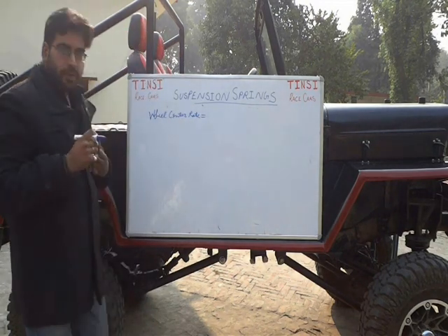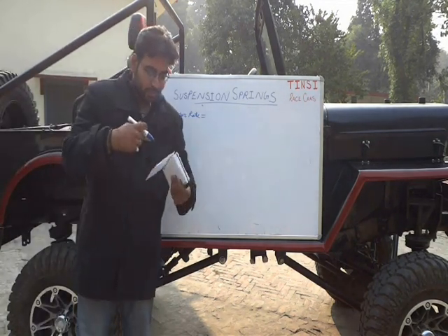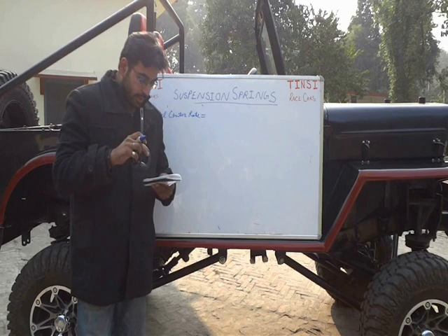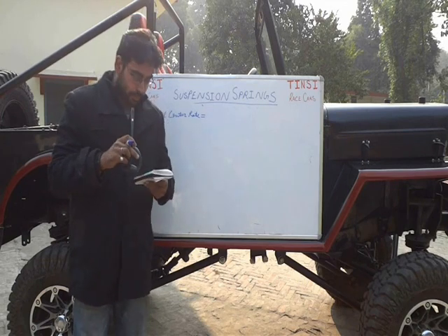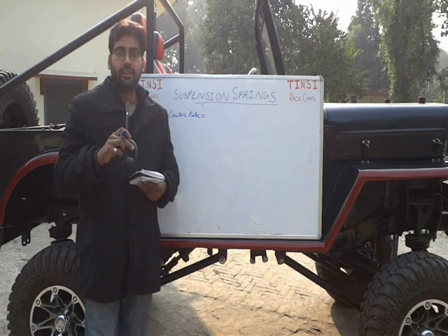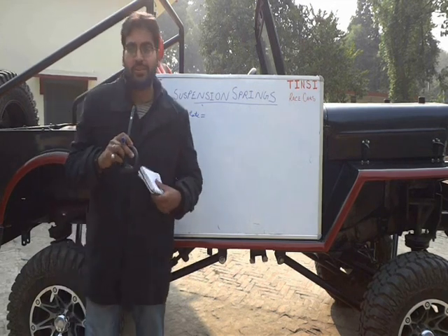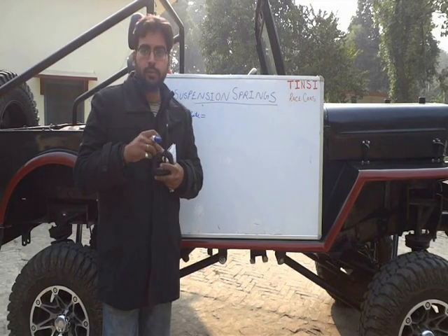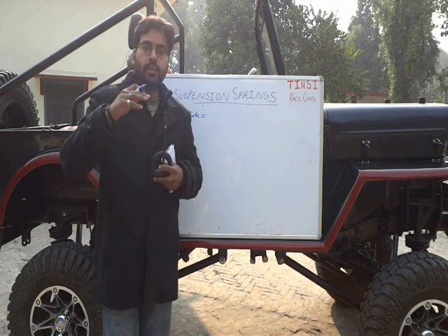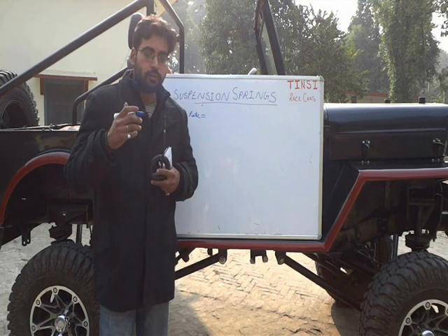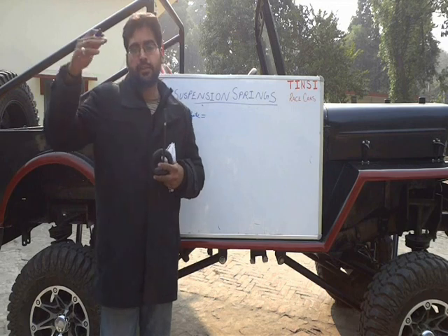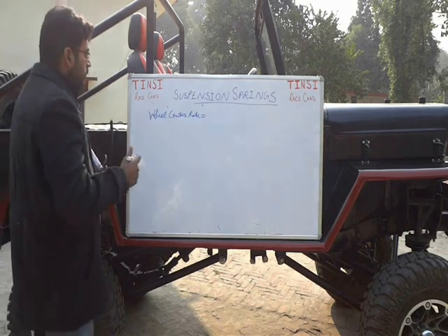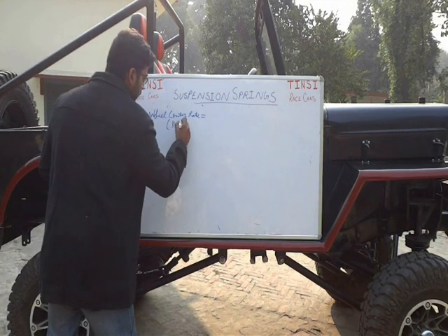It has a typical definition that I've written down because I couldn't remember it: vertical force per unit vertical displacement at the location along the spindle corresponding to the wheel center line, measured relative to the chassis. So basically we are calculating this force at the wheel center, meaning the force between the wheel center and the chassis, which is our springs. This is what your wheel center rate is. Let's write it KW.